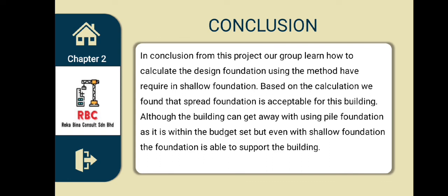In conclusion from this project, our group learned how to calculate the foundation design using the methods required in shallow foundation. Based on the calculation, we found that a spread foundation is acceptable for this building, although the building could get away with using a pile foundation as it is within the budget set. But even with a shallow foundation, the foundation is able to support the building.